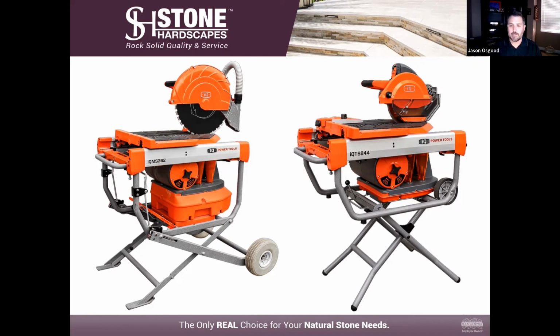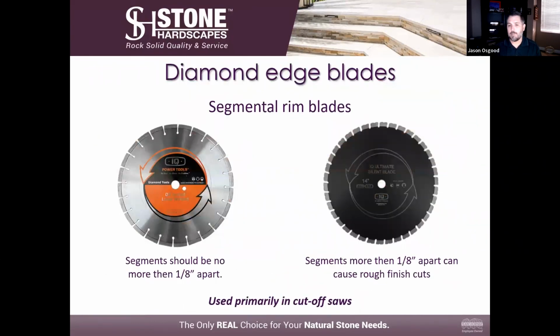And the last thing is, I want to talk a little bit about blades themselves. We recommend diamond blades by far. And there's really 2 ways I define the diamond blades for our industry: segmental rim blades and continuous rim blades. On the left here, you see a segmental blade for natural stone, for porcelain tile. With a segmental rim blade, the rim itself is broken into multiple segments, as you can see. The segments should be no more than 1/8 of an inch apart.